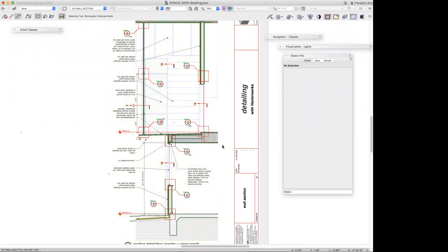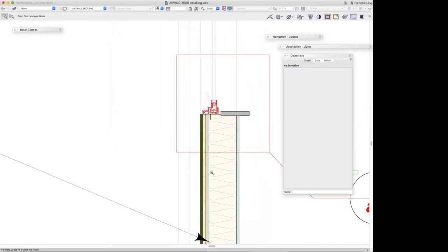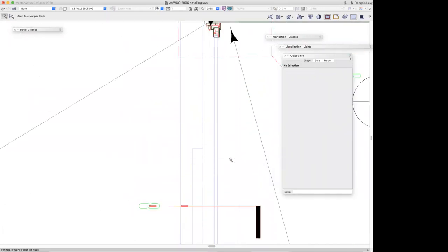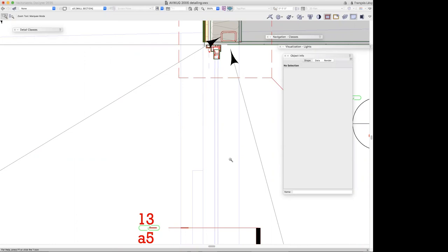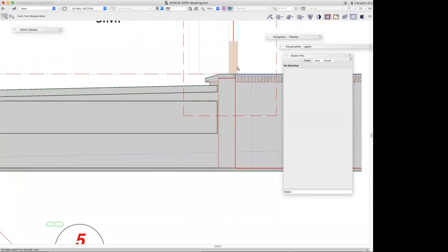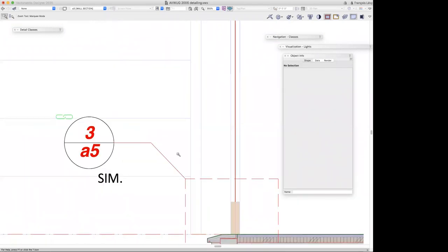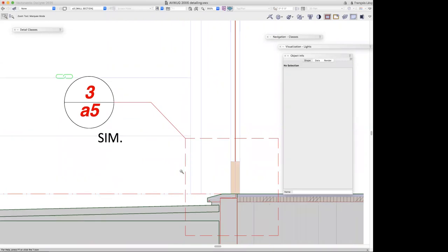So the advantage of having this 2-dimensional content to some of your symbols is that you can show greater detail within your section viewports, because you're swapping out more detailed information for the coarser geometry. Now, in most cases, it's just fine to have a simple plug-in geometry here and then key in a detail back to the sheet of details that you've drawn, as I have over here.